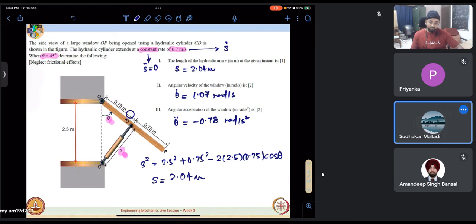So its velocity at every point will change with respect to the observer, right? Let us say this is the point where it is at this moment, at some instant. Since it is changing at every instant, we have to define the instant where we want to analyze it, right? So we know theta dot. Let us say it is at point D at this instant. Can we get the velocity of this point based on theta dot and the distance from the pivot? We'll be able to get that. It is just a matter of adding the vectors in order to get it.